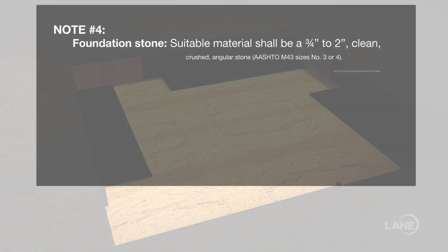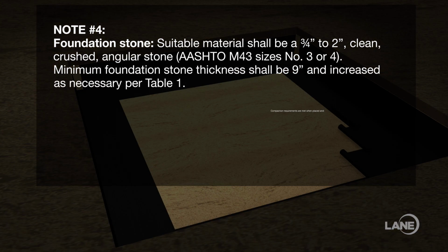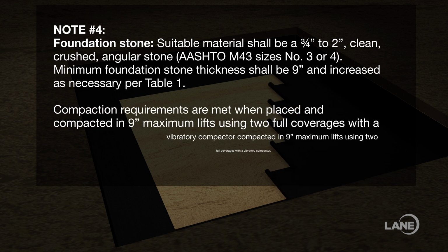Note number 4 on the cross-section detail identifies the minimum foundation stone thickness that is increased as necessary per Table 1.